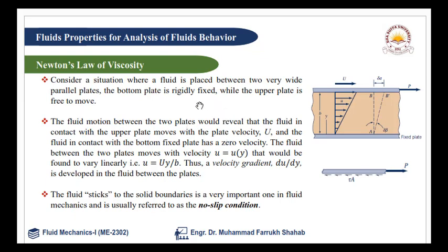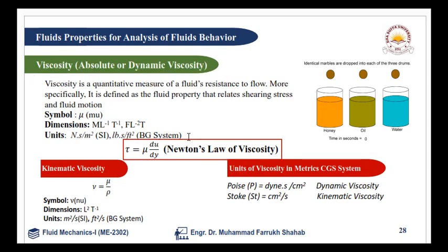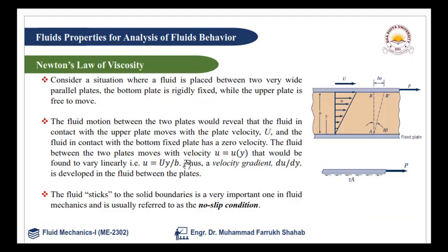now this is the important topic to understand, Newton's law of viscosity. As you remember, I showed this equation to you, which is tau equals mu du upon dy, Newton's law of viscosity. Now in this topic we will be deriving these relations. Let's consider a situation in which the fluid is trapped between two plates. These two blue things are the plates, and in between the fluid is trapped, which is shown here.